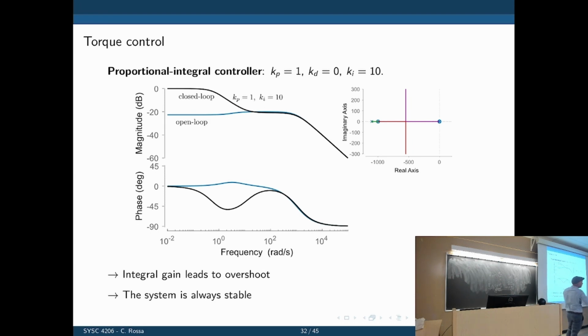negative zero. So what's the implication of having a PI controller instead of a P controller? Overshoot. Look at the root locus. For past a certain gain, there is going to be some overshoot, and for some applications in haptics, that's probably not what we want.